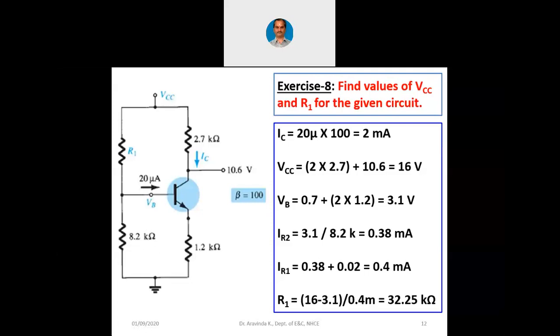Out of the three terminals in a transistor or BJT, till now we have been discussing the circuits where at the base we give input, at the collector we take output, and that is when we bias the circuitry so that we will have a Q point which is VCC by 2 and IC set by 2 ideally, and the emitter is common. So this is called common emitter configuration. Please recall whatever you have studied in basic electronics in the first year. Till now whatever we have discussed is common emitter configuration.